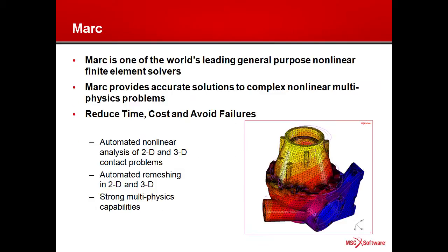Now Marc was the original nonlinear finite element solver. It's capable of solving some very large problems. The solvers inside of there, some of them have gone into Nastran, some of ours have gone into Marc. It's got this automated nonlinear contact. This is the most important thing, is that for the NVH person, you don't have to do these contact pairs or figure out who's going to touch who. The code does it for you very efficiently. And there's this automated remeshing. I've got some examples here to show you why it's important.